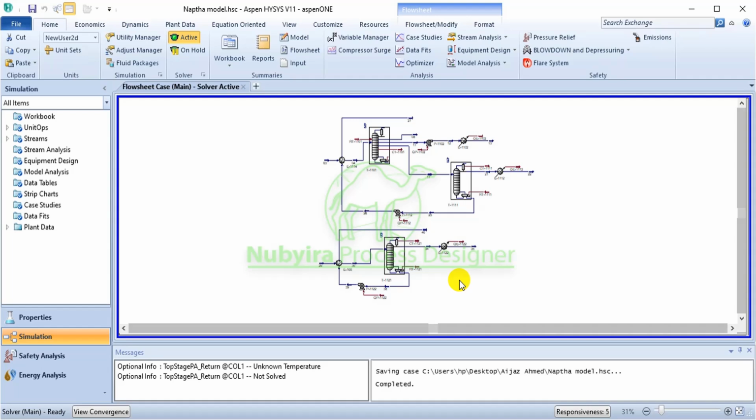So today I am going to be working on a hydraulic tray design on a distillation column. If you want to design a tray or packed distillation column, to design the packing heights, and you just want a preliminary design with the material balance and energy balance simulation that you have done with the software, and you want to calculate a tray design or hydraulic design for the column based on the material balance result after you converge the distillation column in Aspen HYSYS.